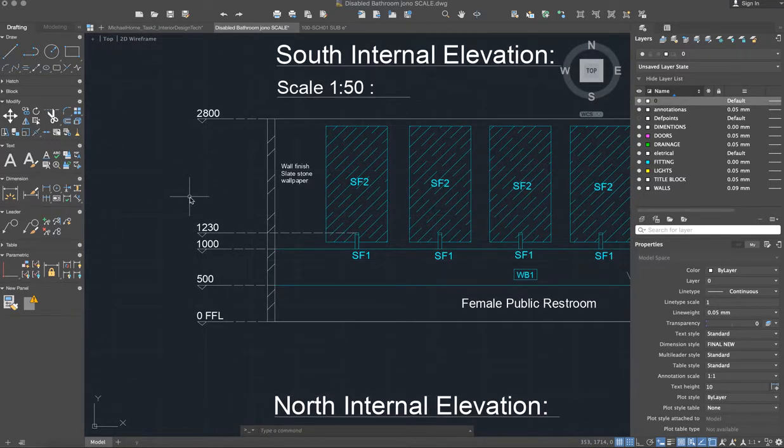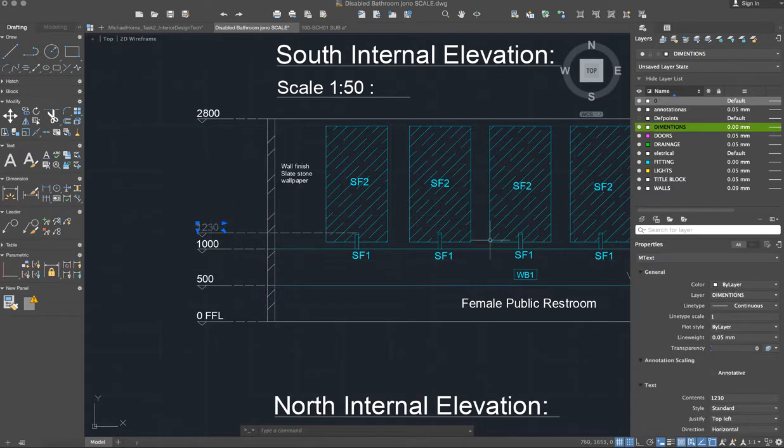Let's check the actual scale here. Let's just see. DR for distance. If I go from here to there, that's showing us 50, not 500. 100, not 1,000. 123, not 1230. 280, not 2800. So this says to me you've scaled this by about a factor of 10.